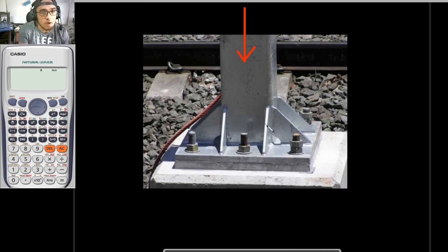So what is a base plate again? As per the definition that I have read a while back, the column base plate is the critical interface between the steel structure and the pedestal. If this is your pedestal, a concrete pedestal, the transition from the steel section in compression to the column pedestal is the base plate. The use of the base plate is to distribute the load.